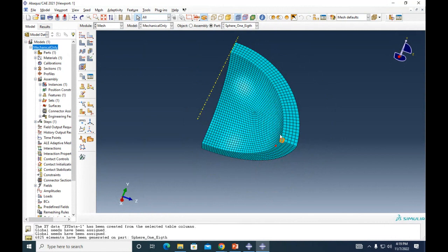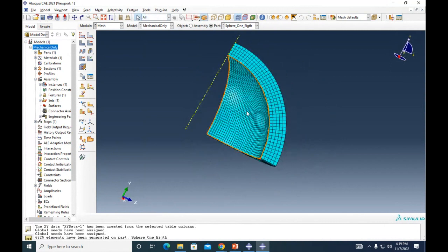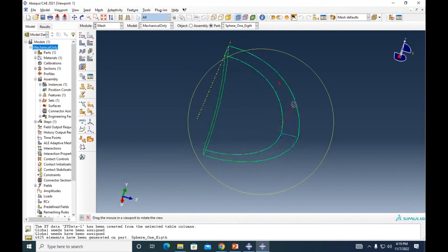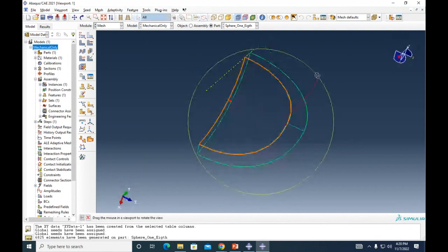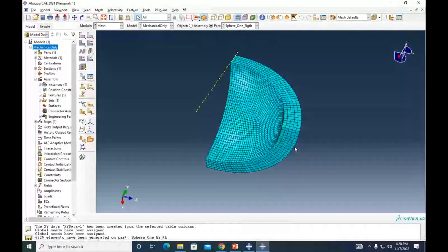It can. So, does anyone remember when we did trusses? If you have a symmetric truss, what do you do in the middle? You add rollers. So because this edge in here, this edge in here, and this edge in here, they correspond to symmetries. I'm gonna have to add roller conditions in each one of those. Okay, so let's do that. Let's do the easy one first.